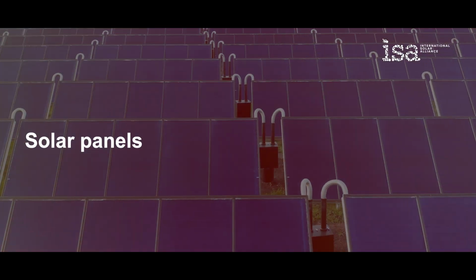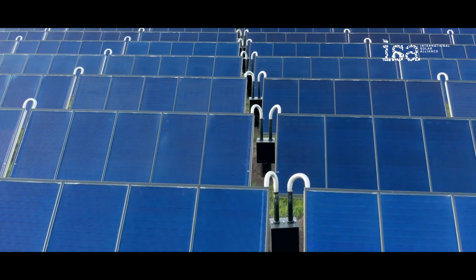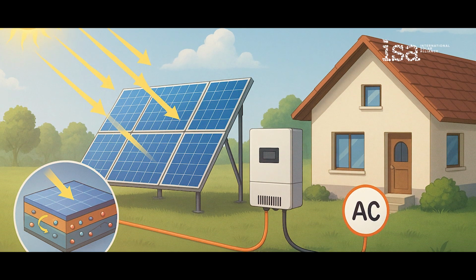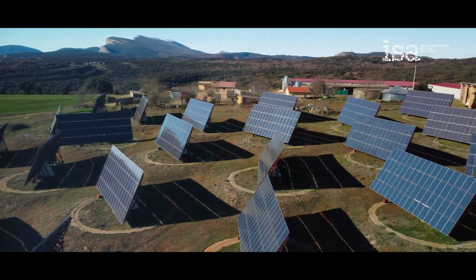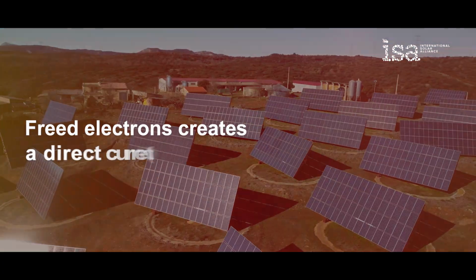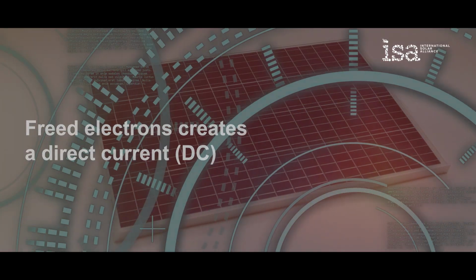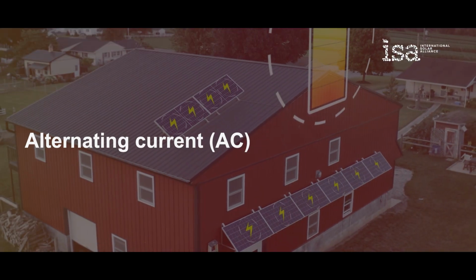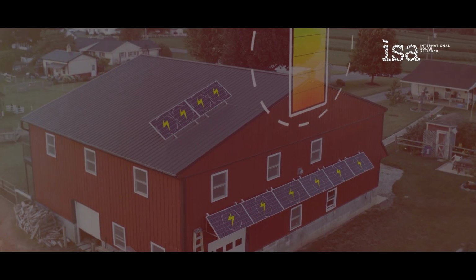Solar panels convert sunlight into electricity through the photovoltaic effect, where photons from sunlight strike semiconductor materials, like silicon, in the solar cells, releasing electrons. This flow of freed electrons creates a direct current (DC) electric flow, which is then typically converted to alternating current (AC) by an inverter to power homes and appliances.